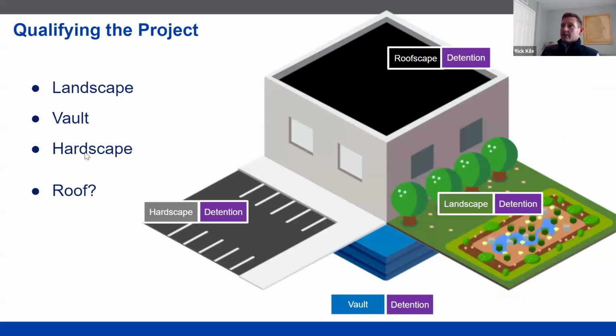But we want to qualify that, right? Building on top of structure, be it a vegetated roof or pedestal paver deck, can be more expensive than doing similar type applications at grade. And when we're talking about stormwater, that's also the case. And so I don't think managing stormwater on the rooftop is a great solution. It's not applicable to every project. And so if we have the opportunity to manage stormwater in the landscape, you're probably going to do that first. It's least expensive, via that detention or that retention pond.